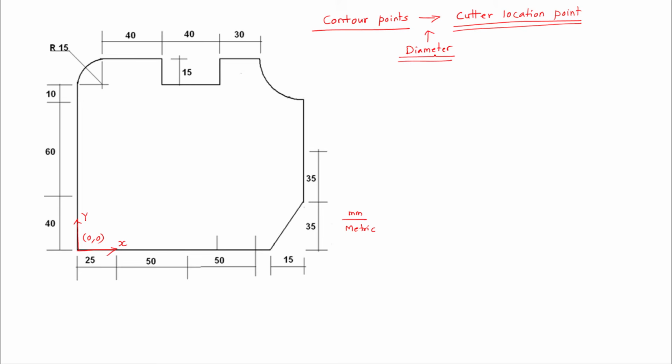Now, as per the syntax of the CNC part program, we have to give the information about these points only. So let us first find out the number of points which are to be communicated to the part program. So this is point number 1, 0, 0, this is P1, this is P2. So P2 has X 0 and Y is 110.